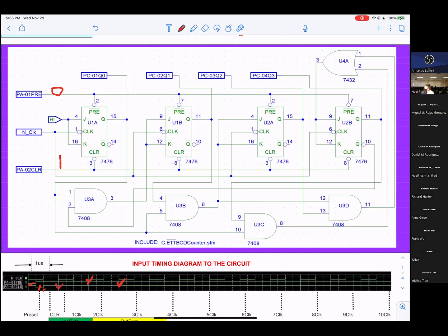And now you see, looks like everything is okay. 0 in here, 1 in here, okay? And the output, they are coming out, okay? You can get a 0, 1 here, 1 here, 0 here, 1 here. So the test still failed. Now they fail on U2 pin 5, 0. You want it to be a 1.